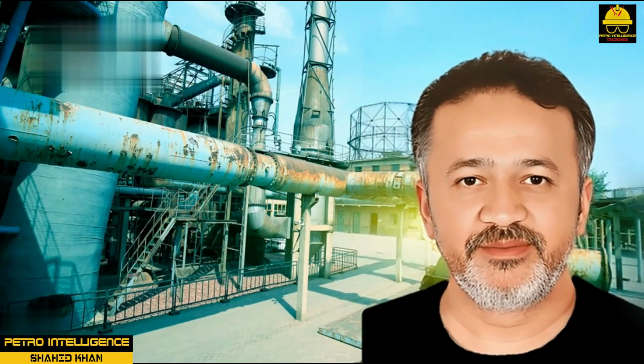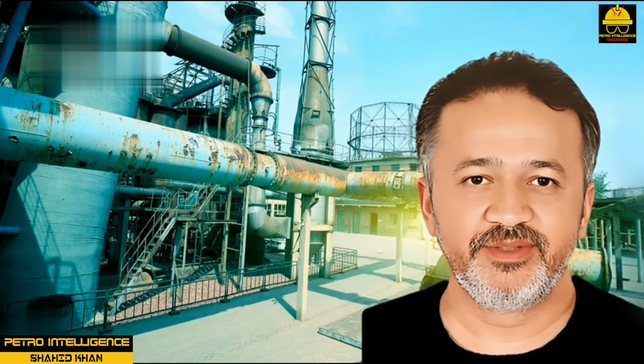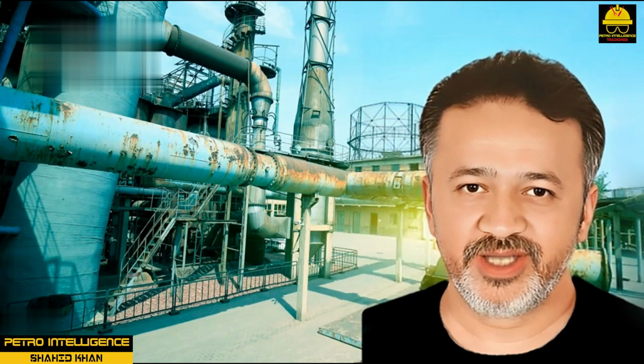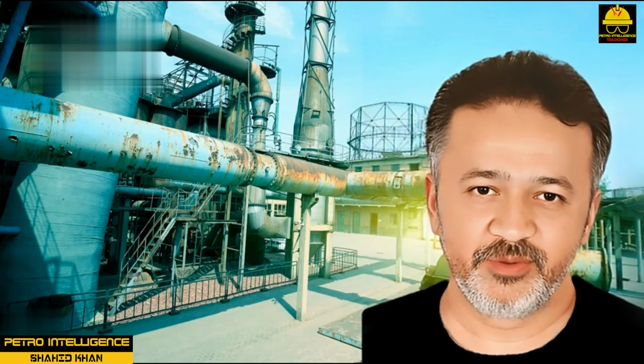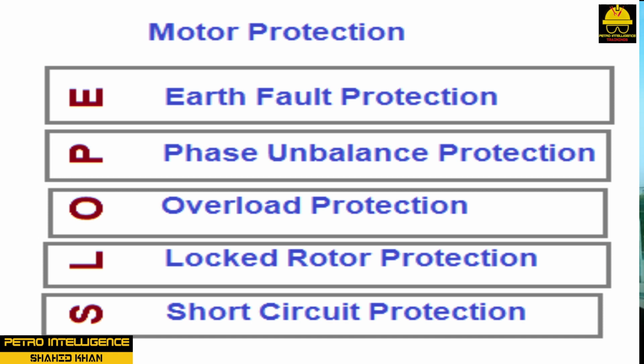Motor protection. In addition to mechanical energy, electric energy can also be converted to heat. This is what happens in a toaster or an electric stove. The amount of heat produced is proportional to the product of the current squared times the resistance, I squared R. The household fuse operates on the principle that it is the weakest link in the circuit. When the current gets large enough to nearly overload the circuit, the fuse burns out and interrupts the circuit.